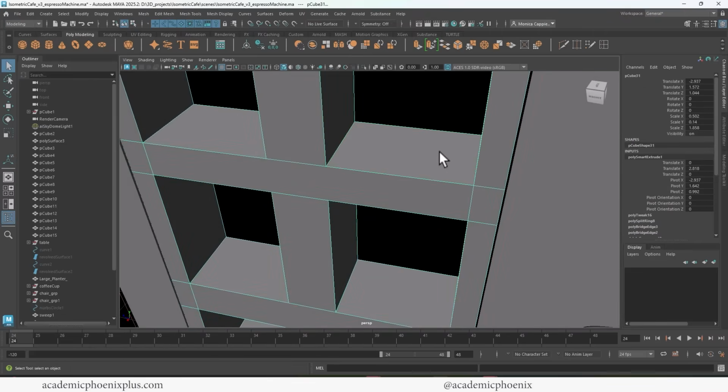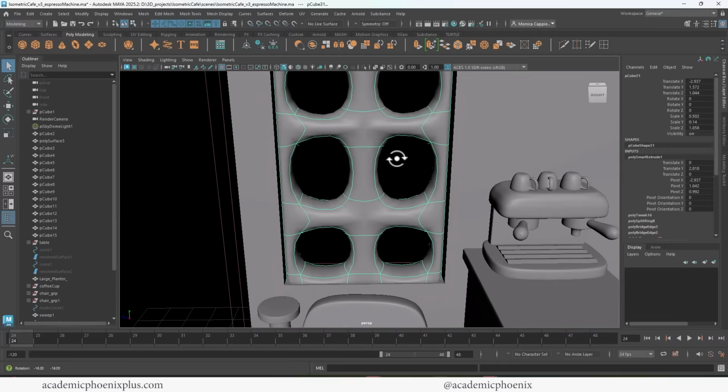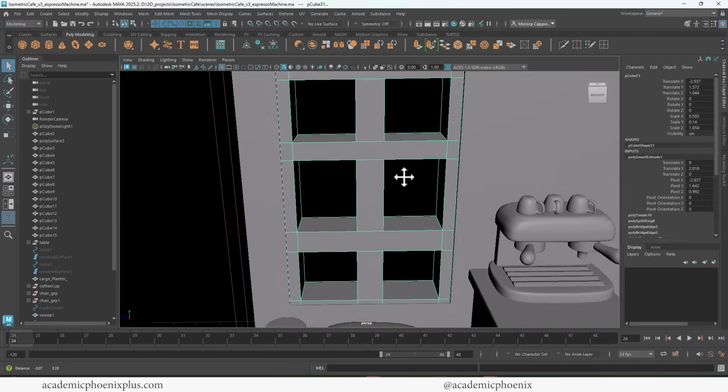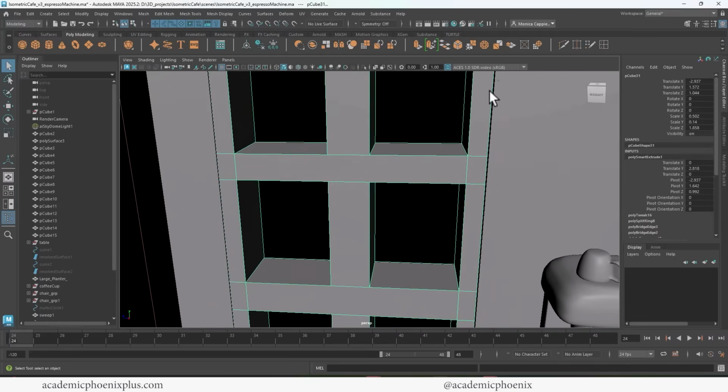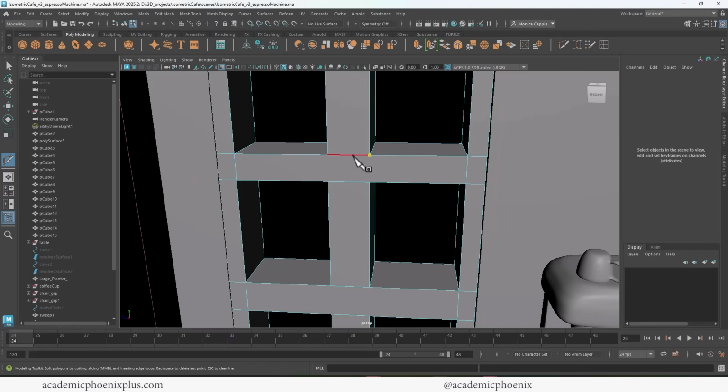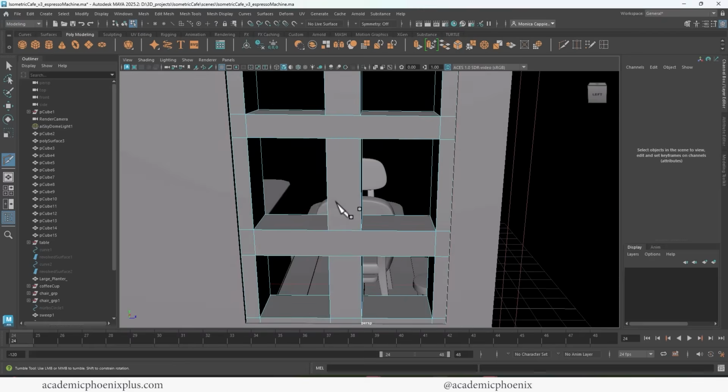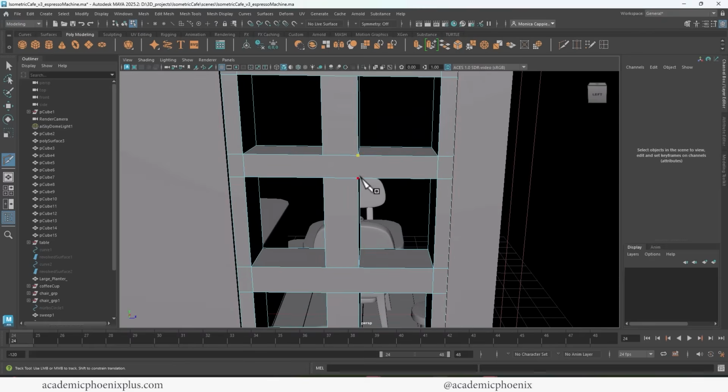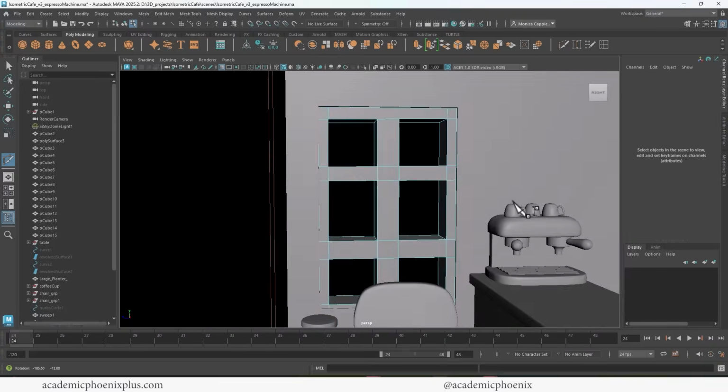Right? So if I go to object mode and I press the number 3, you can see that it actually merged it all together. Now it doesn't look so hot, and we do have some n-gons that I need to clean up, but in general, that's a great way of getting intersecting geometry really quickly. So that's a relatively new tool. It's a lot of fun. Definitely recommend for you guys to check it out. It's called Smart Extrude. So now I'm using the multi-cut to create my quads.